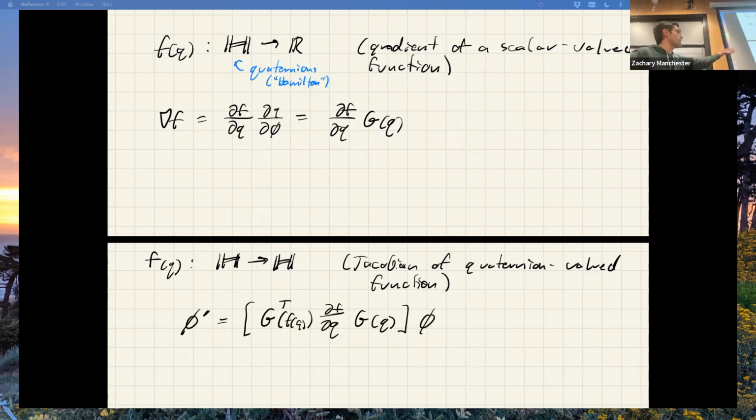Okay, so the way I think about that is if I have dynamics, I'll compute the A matrix in the normal way, that's partial F, partial Q. And then on the right-hand side, I slap on this attitude Jacobian at qk. On the output side, if the nominal output is qk plus 1, I evaluate g at qk plus 1 and slap it on the output side, and it gets transposed. Cool. That's it. Straightforward. And this thing we're going to call grad f here, or we'll use this notation.